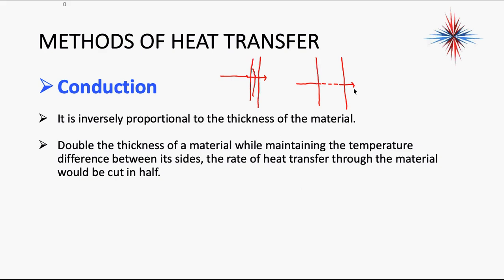That's why a lot of construction has gone to 2x6 or even 2x8 on outside walls. It used to all be 2x4. But again, we double the size of the wall, and the heat transfer is cut way down.